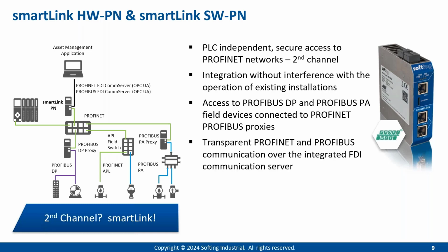So what we provide here on the north side for the transparent Profinet or Profibus communication is an integrated FDI communication server, which then allows the asset management application to send any commands again to the devices. As already mentioned, the product is available as a hardware appliance and software module.